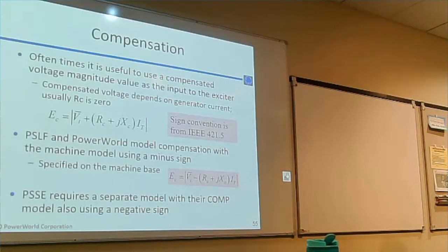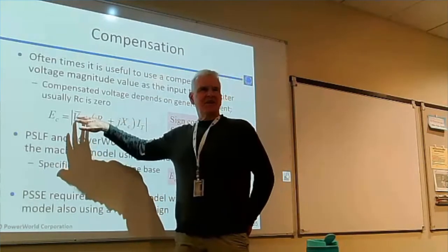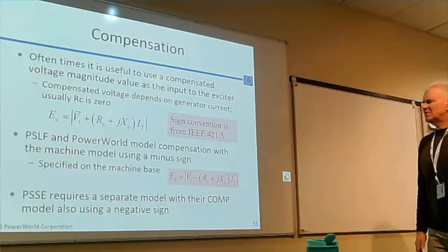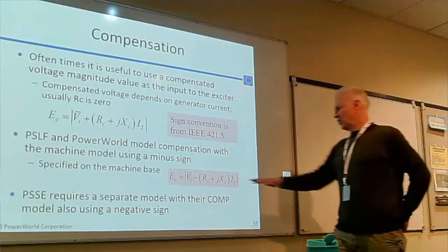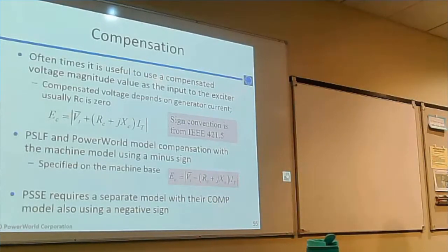One of the confusing aspects here is compensation. There's a sign convention here. The IEEE 421.5 standard is like that. PSLF and PowerWorld have a minus sign there. Yeah, all the software vendors do not follow the standard. I don't know why they don't follow the standard.